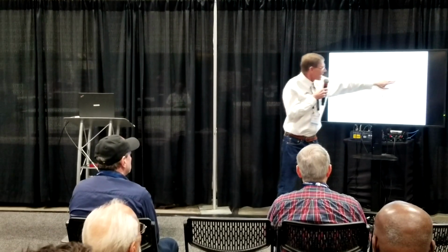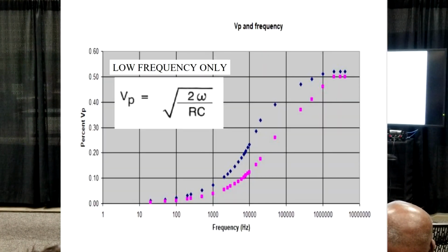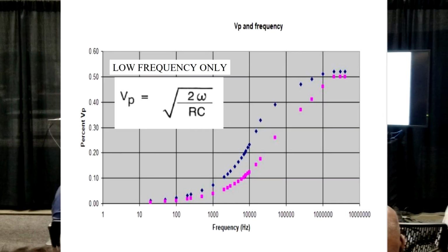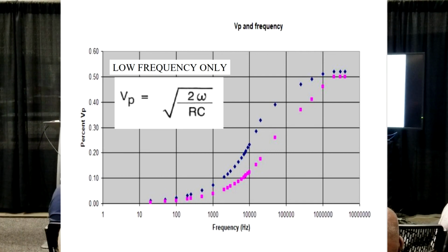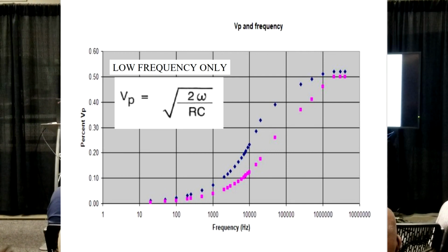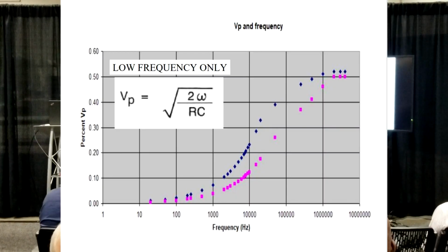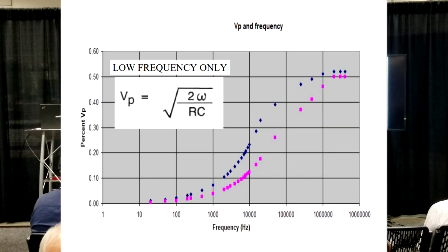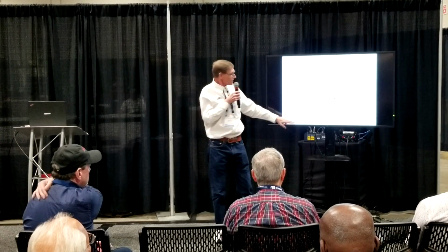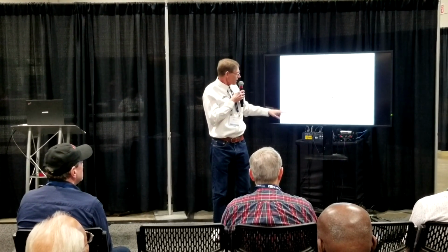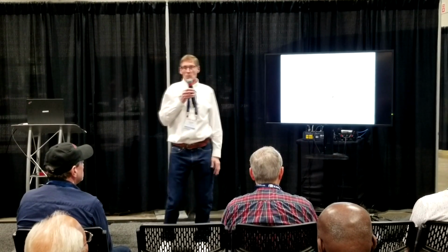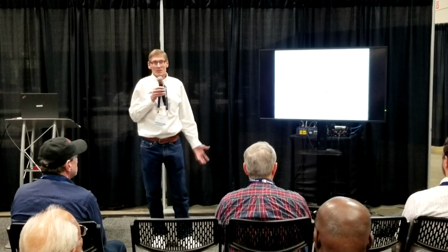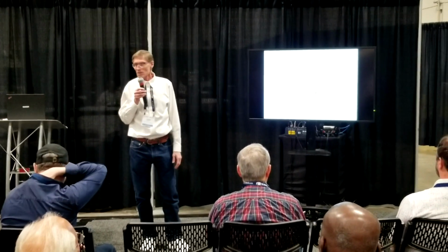This is one design, and you see its characteristic slope. This is another design, where I tweaked that equation that I showed you in the previous slide. But notice you can only tweak it so much. Why? It's going to go from RF limiting velocity, based on the design, to 0. Here's 10 hertz, look at my velocity, I'm at what, 4 or 5%? Well, that's pretty close to 0, so it's definitely going to 0. The velocity of propagation at DC is 0.